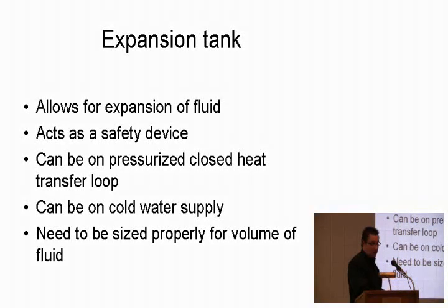So you'd have an expansion tank on the actual water side of your system. The tanks are rather similar in nature, pretty much the same in their whole design. The one thing is it does need to be sized properly for your volume of fluid.